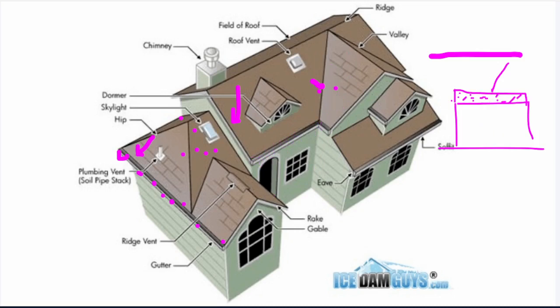And let me remove them. Please keep in your mind the slope and direction that have been created. Look at the chimneys. And the other problem that you should respect, and you didn't put it: all the chimneys must come to the top of the roof, not necessarily out of the roof. So we need to see at least the chimneys or the other ducts coming outside of the roof. We need to see all the ducts, okay? Specifically ventilation, the ones that need fresh air.